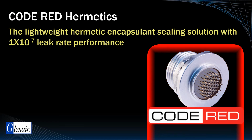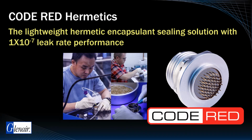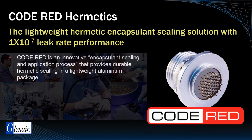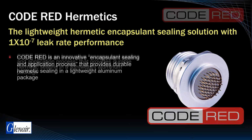CodeRed is the Glenair branding for our signature Encapsulant-to-Metal sealing hermetic technology that delivers 1 × 10⁻⁷ leak rate performance at a fraction of the weight of conventional stainless steel and Kovar glass-to-metal seal hermetics. CodeRed is an innovative encapsulant sealing and application process that far surpasses historically poor epoxy sealing results.